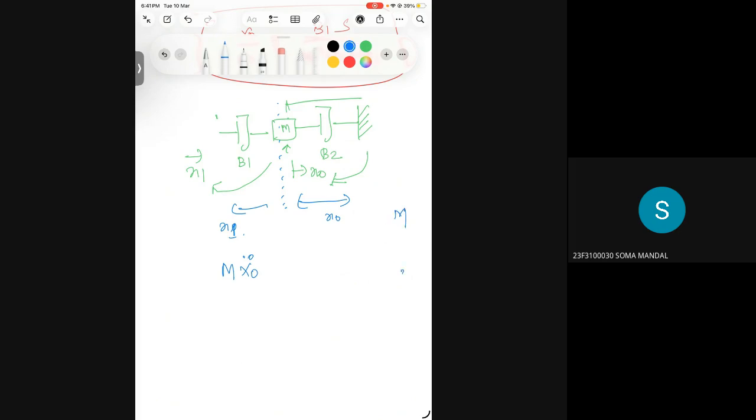These are all the parameters in your system, right? So mass, the spring is called K, and the damper is called B. Everything is the same, B. What this mass will do is create a force Fm that is proportional to the negative of the acceleration in your system. The damper will create a force that is proportional to the negative of the velocity in your system. The spring will create a force that is proportional to the negative of the displacement in your system.